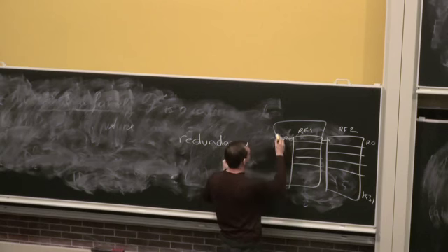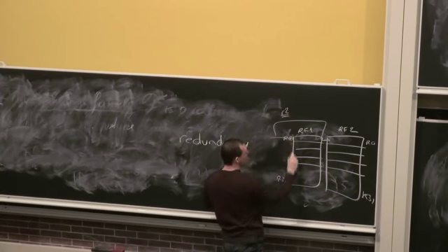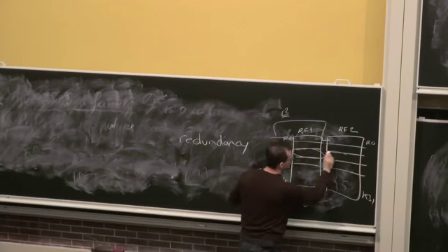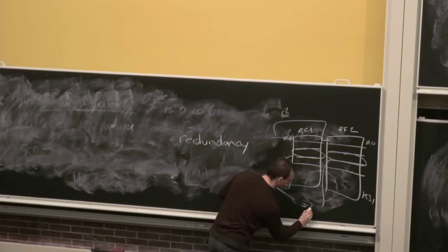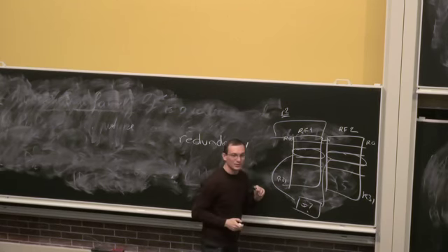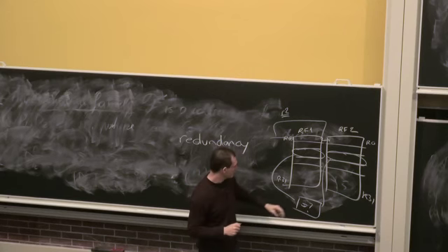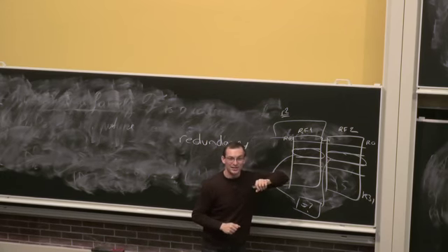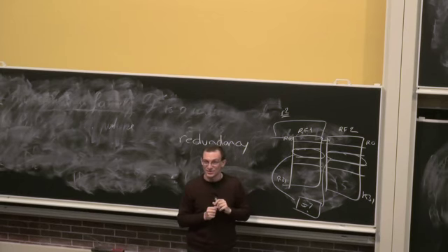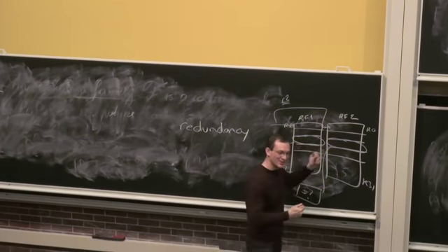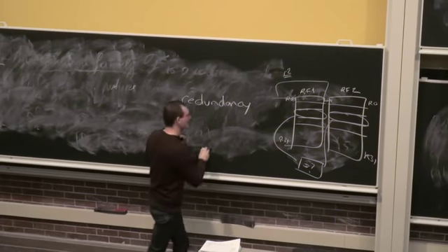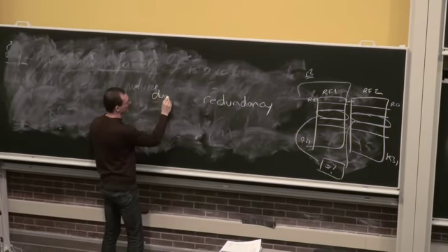Basically, when you read, let's say the instruction is reading from register 2, it can read both copies of register 2 and do a comparison, right? If both copies are equal, then the hardware can assume that the value did not get corrupted by some error. Yes? If they're not the same, how do you know which one's right? So if you have two copies, you don't, right? So this is called dual modular redundancy.